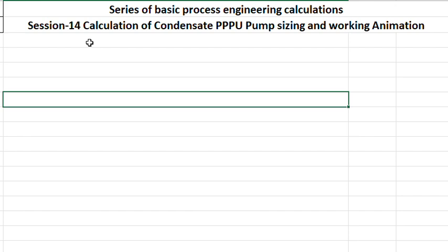That pump can be used with approximately 3 kg of steam per ton of condensate, and it can pump the condensate up to 100 degrees Celsius.